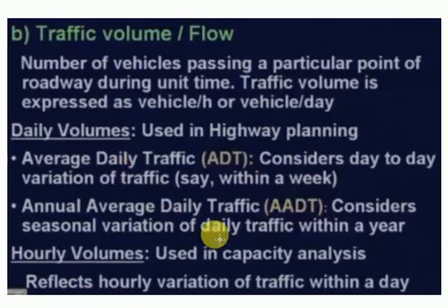So various types of volume measurements are there, but the common one is AADT, that is the annual average daily traffic. Here the average 24-hour traffic volume at a given location over a complete 365 days in that year is calculated. That is the total number of vehicles passing a particular site in a year divided by 365. That is the average annual daily traffic.